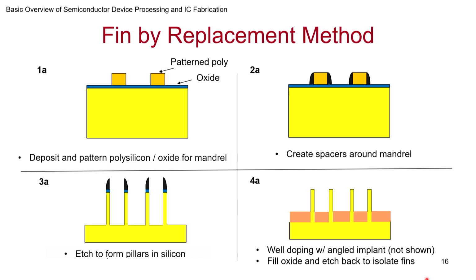I hope you are able to see that if you are being creative, you can come up with a different way of getting the same thing with the existing resources. Mind you, lithography has not changed. With the same lithography, using some similar structures we saw earlier in this context, you build a closely packed structure. So this is how fins could be built. Creativity is continuing, and as we speak, people are developing better and better ways of doing things.